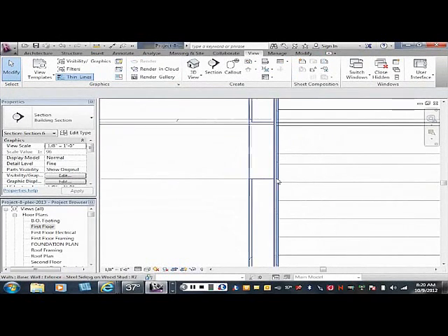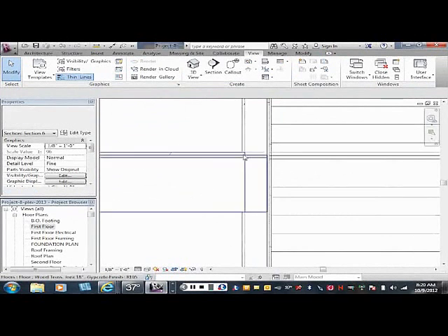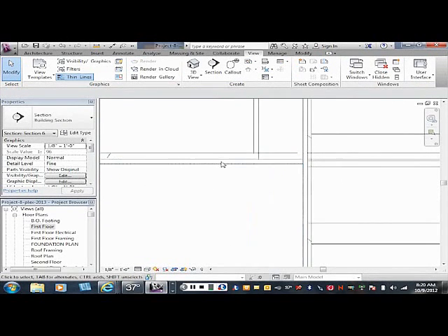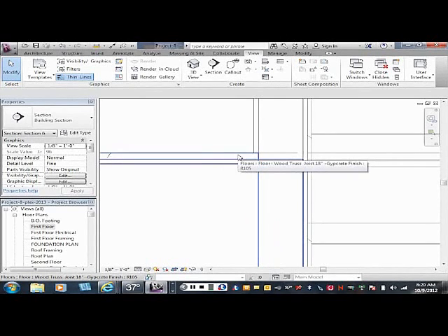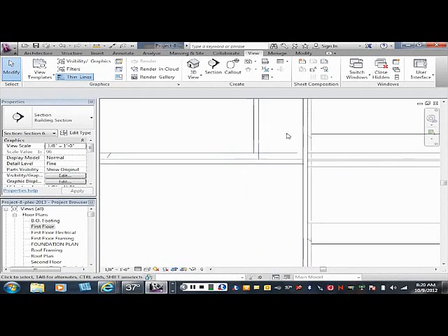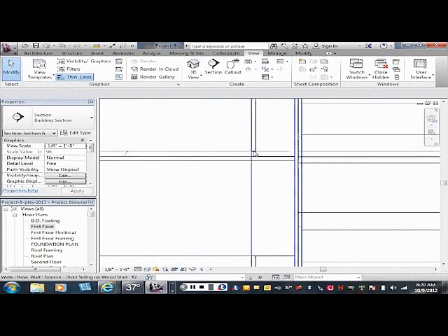The joist is going across, or the truss joist here, and you can put in the details. Up on the top, you'll notice that the subfloor went under the wall, but the gypcrete did not, because we put the gypcrete outside of the core of the floor, so it doesn't go into the core of the wall. So cores match up, and outside of the core items do not. So that's kind of what we wanted.